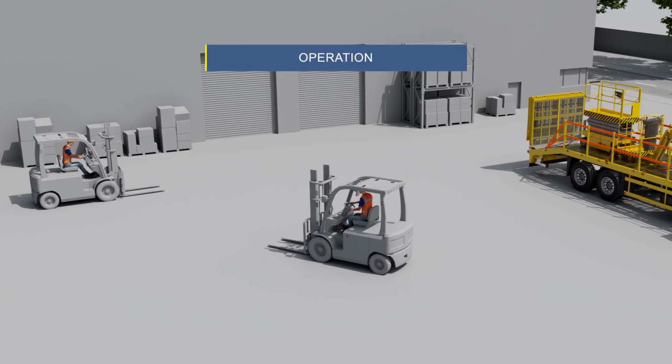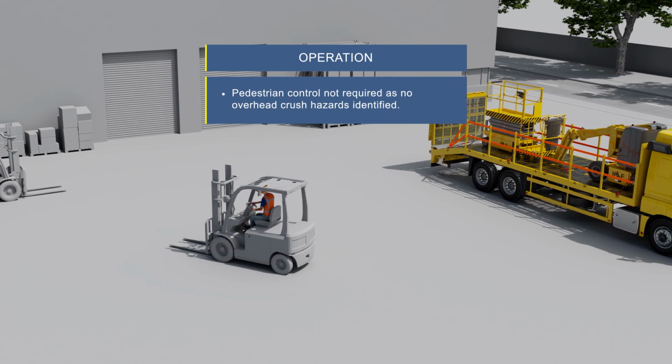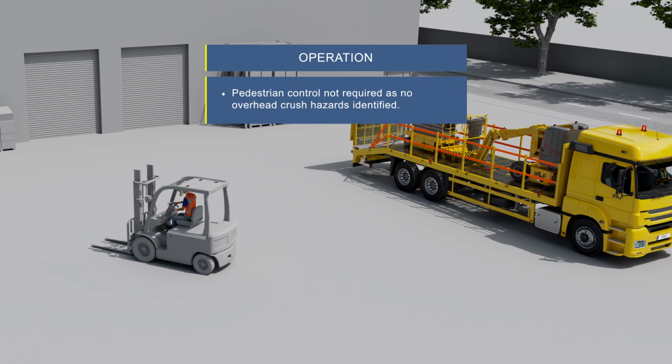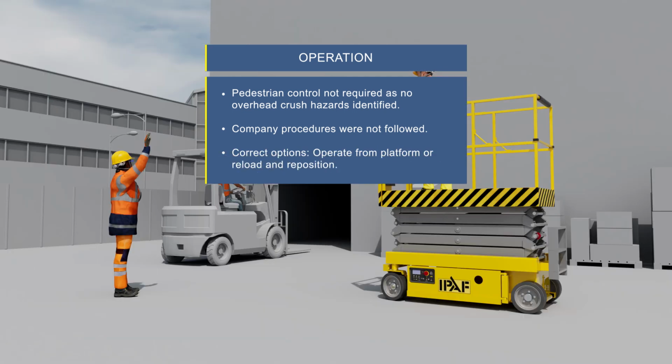The delivery driver was trained and held an IPAF 3A and 3B license. He should not have used the scissor lift in pedestrian control mode, as there were no overhead crush hazards identified on the designated route to the alternative unload area. He should have followed company procedures and either driven the scissor lift from the platform controls position or loaded both mobile elevating work platforms back onto the delivery vehicle and driven to the correct unload area.